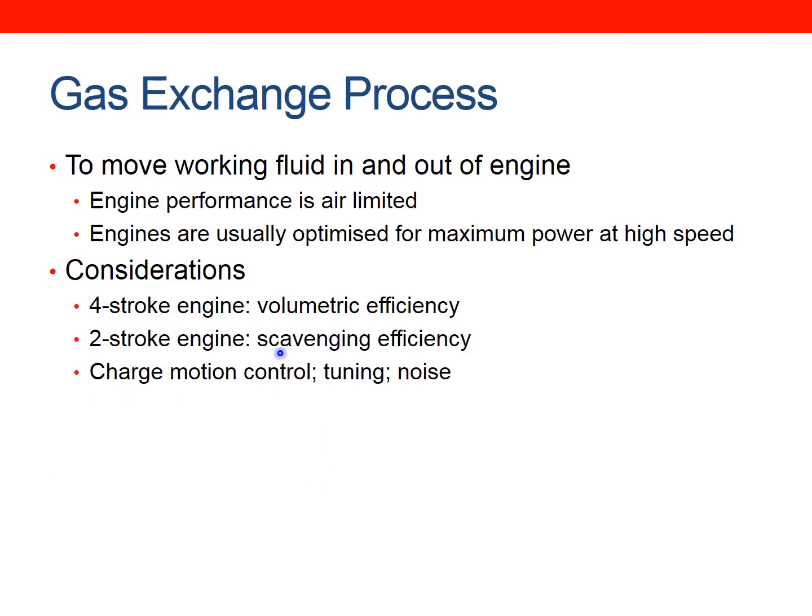Okay, so first, just talking generally about the gas exchange process. What we're really talking about is the ability for an engine to move the working fluid, air in this instance, in and out of the engine. So the engine's performance is air limited. It's relatively trivial to get fuel into the engine. We can squirt more into the intake manifold, or in the case of a direct injection engine, we just squirt more fuel directly into the cylinder. That's easy enough, it being a liquid. But to get more air into the engine so that we can actually burn that fuel, that's what's really limiting the performance of the engine.